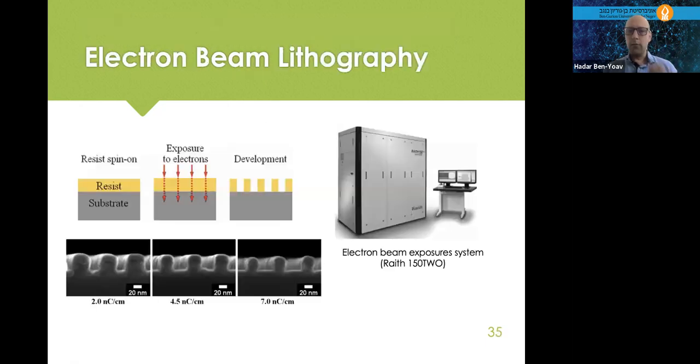And from that, we move out of photolithography and go down to electron beam lithography. So instead of photons shining light that interacts with the photoresist, we have electrons that are being exposed, and they interact with a material called a resist, not a photoresist, because it doesn't react to light, it reacts to electrons. So we pattern the same way as photolithography, just with electron beam lithography.